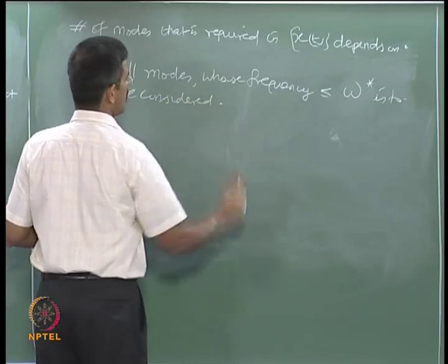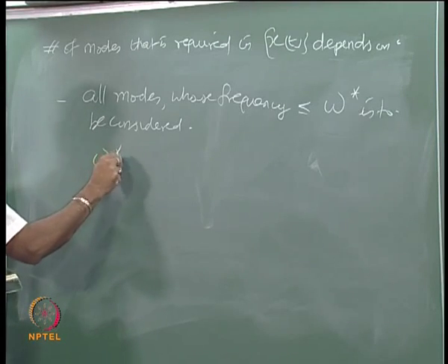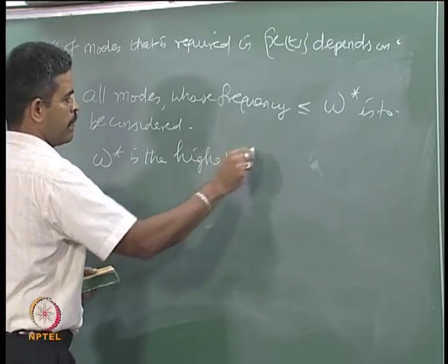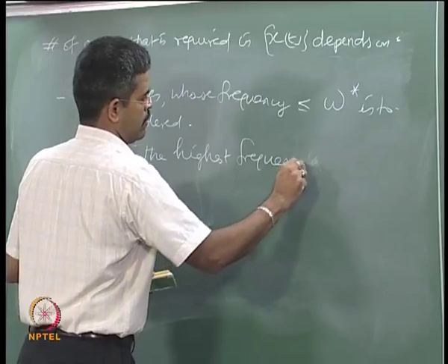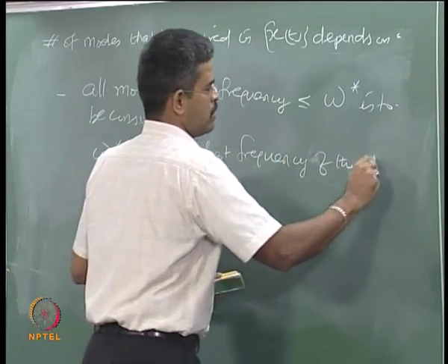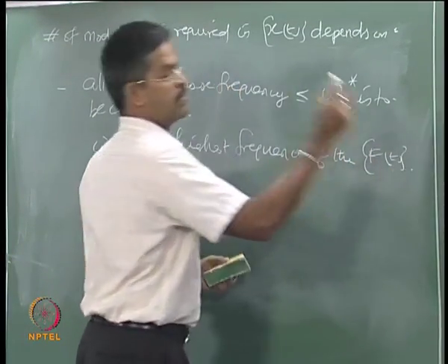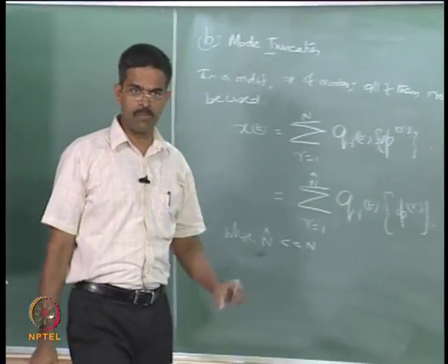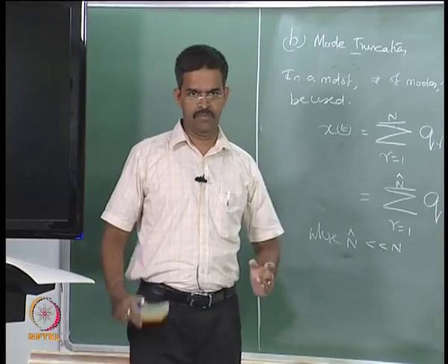Now the question comes, what is omega star? Omega star is the highest frequency of the forcing function, that is the highest frequency content of the forcing function. You must pick up the frequencies till that.